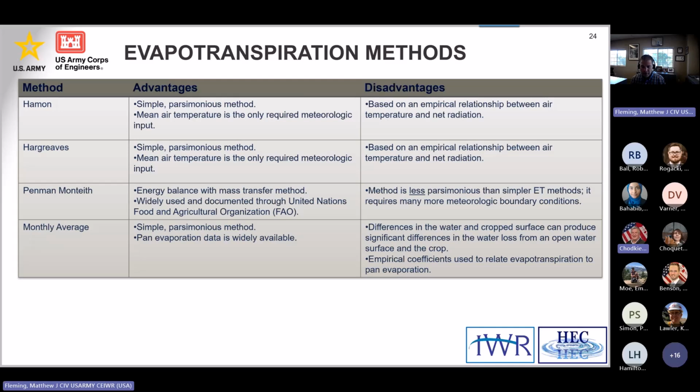You can use those values to parameterize that monthly average table in HMS for each subbasin. There is a global parameter table for monthly average, so if you don't want to go through the HMS tree and define those relationships for each subbasin, you don't have to. You can open up the global parameter table. If you can't find it, just reach out and I'll show you how to get that open.